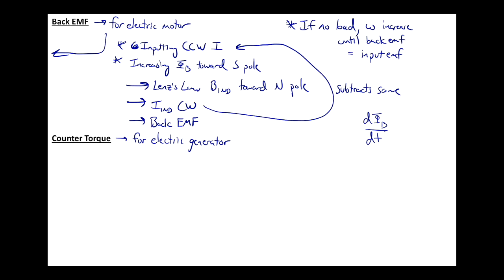When we were talking about the torques on the wire, before we talked about brushes to fix that, did we say that if it was flat, and then it would turn like that, vertical, would it stay at that vertical, or would it flip 180 degrees? It's going to end up aligned with the magnetic field. So the position where there's zero force, if it started like this, and the magnetic field is this way, it'll go that far.